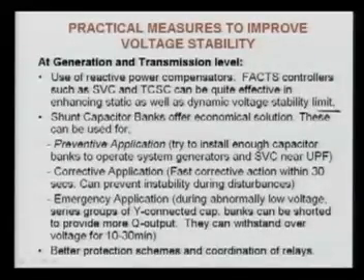In the transmission lines you can use FACTS controllers, and at the generation level you can generate more reactive power if your system is reactive deficit. Sometimes your system may have huge reactive power, especially when the loading of the system is less. In that case you have to have reactors, and those reactors must absorb the reactive power during off-peak loads, because the excessive reactive power charging of the transmission line will give reactive power, and generators are also allowed to absorb reactive power so that we can have a healthy system.